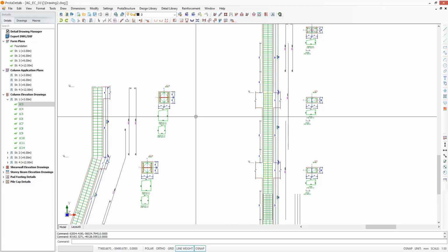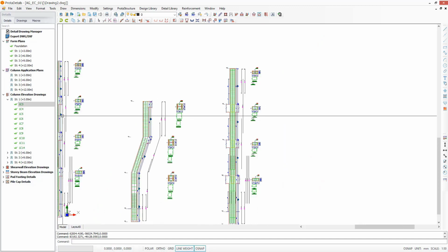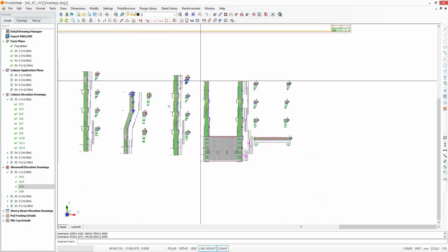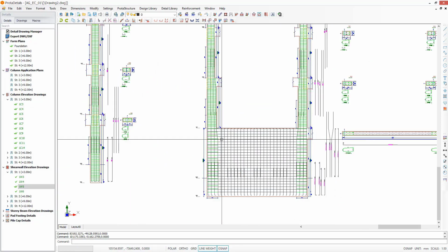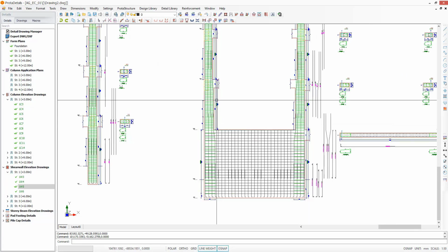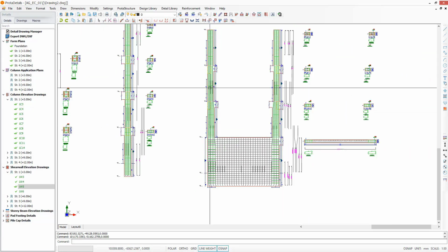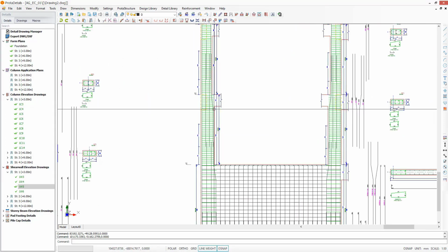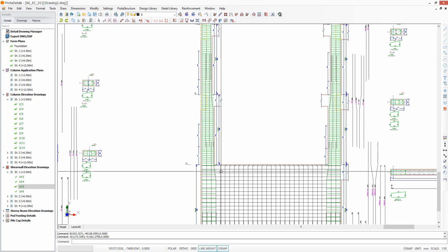But furthermore, you can even see the elevations of columns supported by shear walls. Let's see this one. Again, through the stories, select. Here you can see that the bars are bent into the column, and as the section changes throughout the stories, it just makes the correct detailing through the stories. Also, you can see that the bars that cannot go into the columns are bent back inside the shear wall.